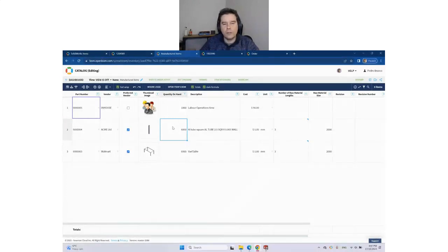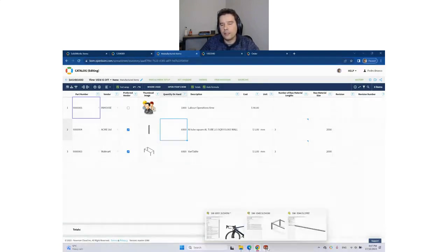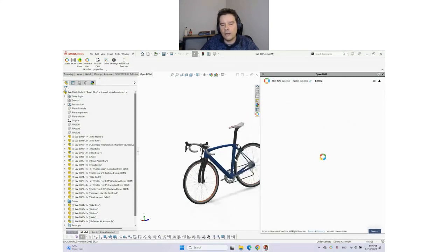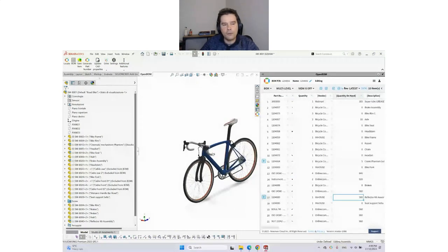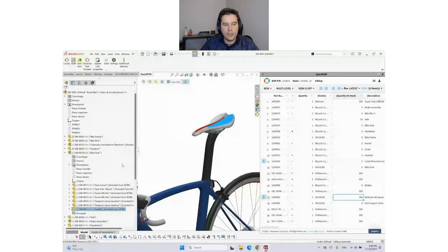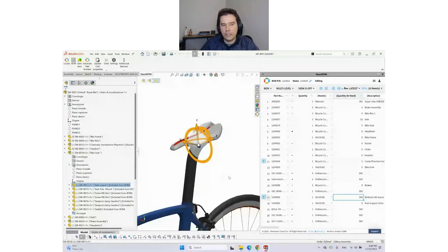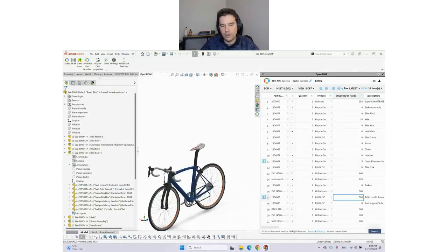So other functions when you move from engineering BOMs or CAD BOMs more into a production or planning BOM, it's also very important that you can start filtering very quickly the assembly levels that you don't want in your bill of material. For example, in this case, we have a purchase assembly where we are excluding from the BOM all those components that you don't buy, you don't care about. So basically, you're already sending the right components to your BOM structure straight from CAD, straight from the engineering bill of material.